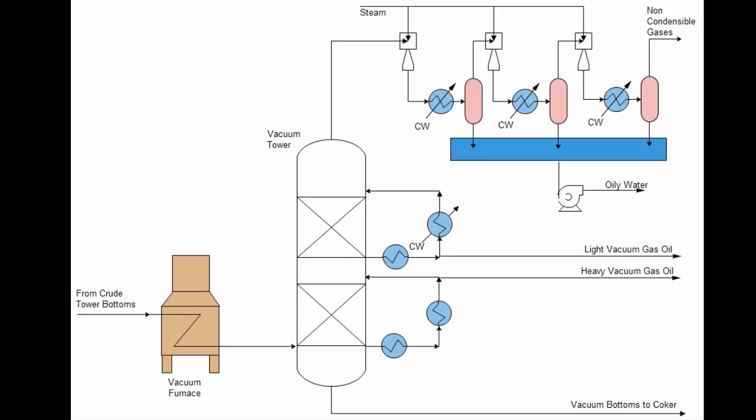How low a vacuum can be reached is directly proportional to cooling water temperatures. The lower the cooling water temperature, the lower the vacuum. Providing additional cooling for the steam condensation system for the vacuum tower is the most important Aggreko application.